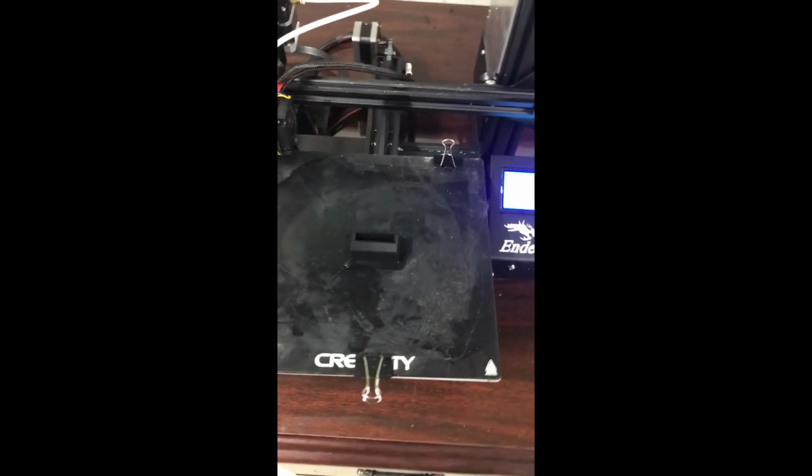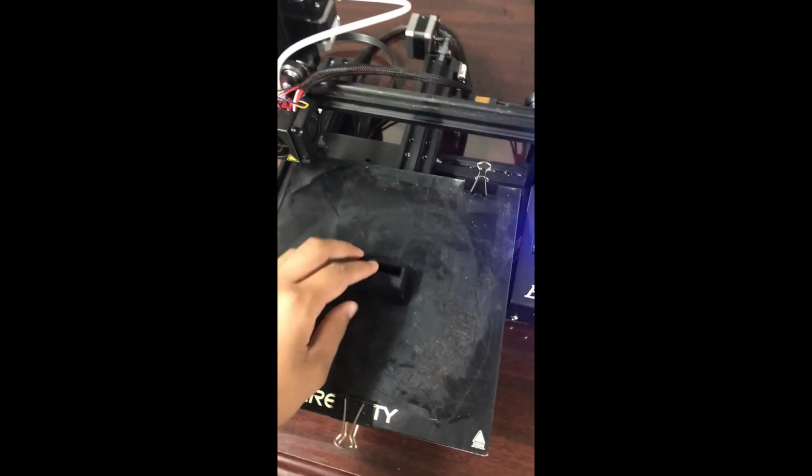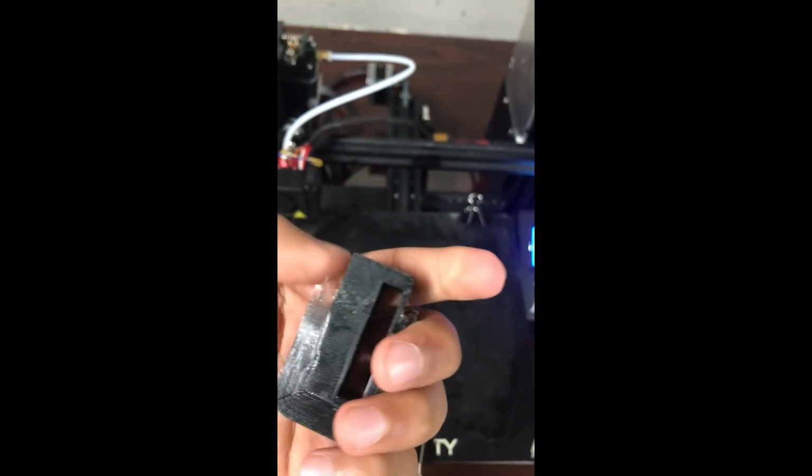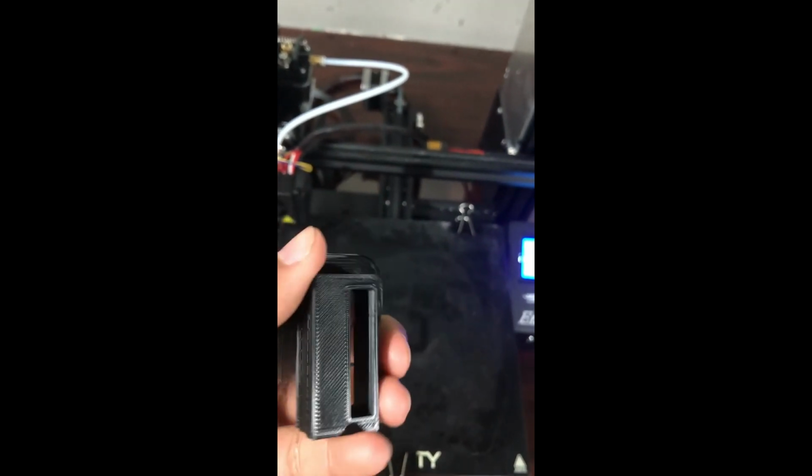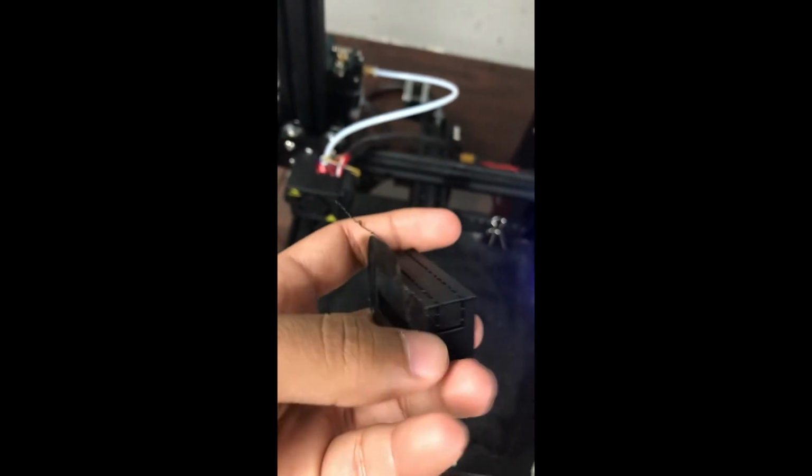So here is my 3D print finished, and now all you have to do is take it off. You see here, this is the brim that I was talking about. The print bed wasn't as level as I wanted to this part to print, but it's still good. Now all I have to do is just peel this off, and you see the support under here. Take something small like a screwdriver or something, just pop that out, it'll be fine.